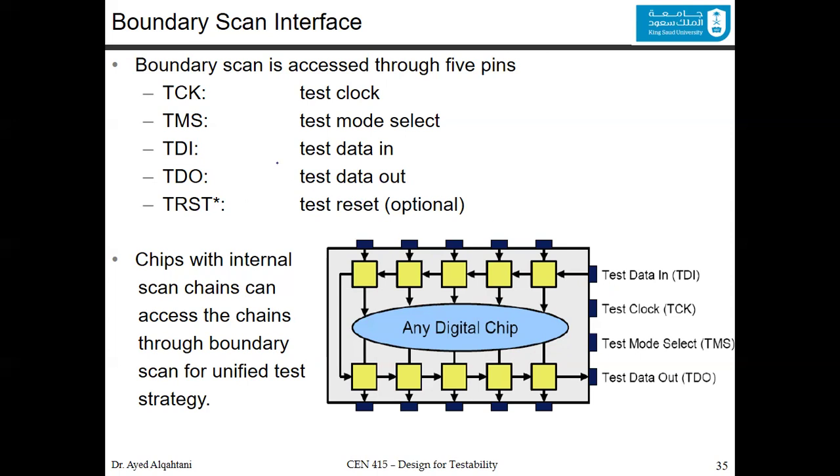You can see here that we make sure that we have these four in this design. You have the TDI going in, shifting all the pins, and then you have the TDO, or the test data out. And you have the test clock also and the test mode select as well. So what happens, again, the same idea for this chip: you serially input the test vector, and you need 10 clock cycles, since the number of pins here is 10, to plug in all the test vector bits.